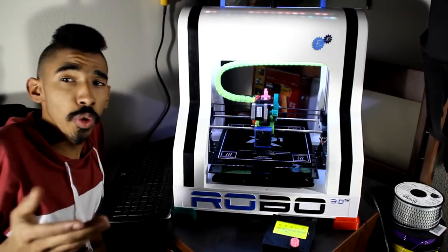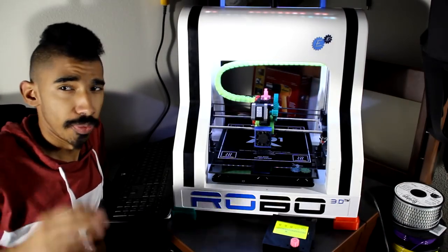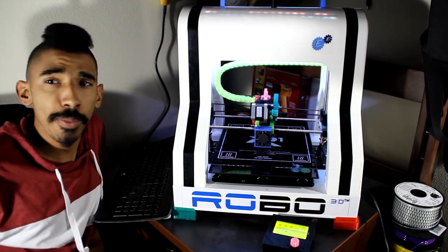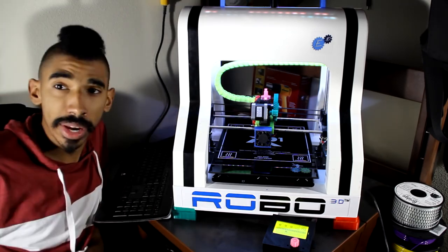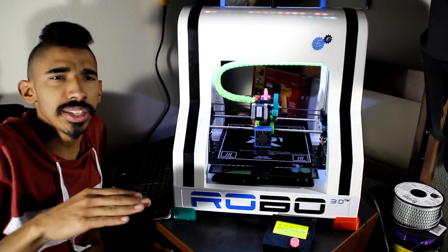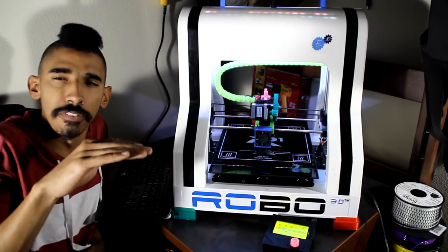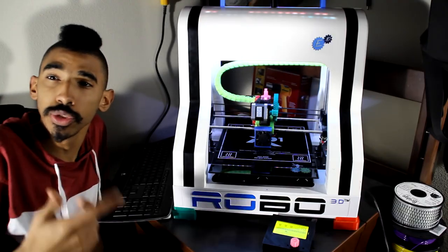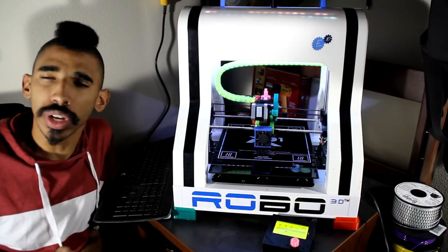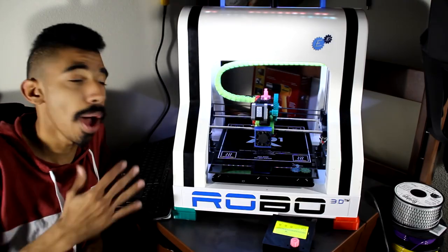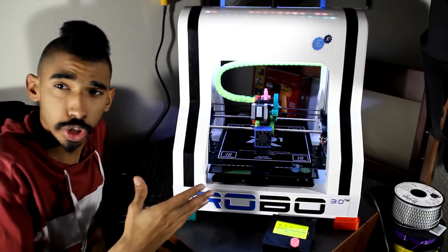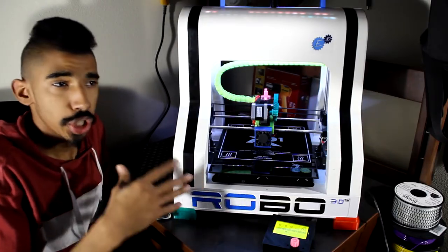Now, if you're one that tunes your 3D printer, you're going to want to know how to do a PID tune. That is using the M303 command. It's not something I'm going to implement right now because I currently have an OK PID tune, but what it does is it heats the extruder up and lets it fall and then heats it up again, and then it gives you a P, an I, and a D value. This is your proportional integral derivative. It is how the power is managed inside the printer to pulse the extruder and the bed to give yourself a very steady temperature.